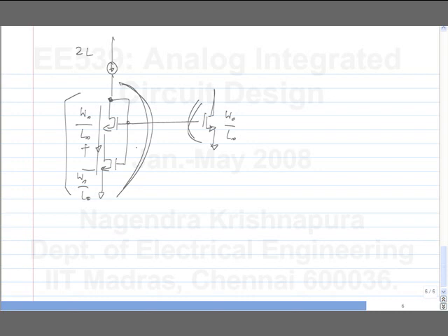First of all, the rule would not apply simply because the drawn length and the fabricated length are not equal. You try to make the ratio of drawn length and fabricated length equal by splitting it, right? Is that what you are trying to do here? Okay, so that goes away. But still, the fields inside are different. The inverse proportionality to L still does not hold, only if you have very long channel transistors. If both are very long channel transistors, it will work.